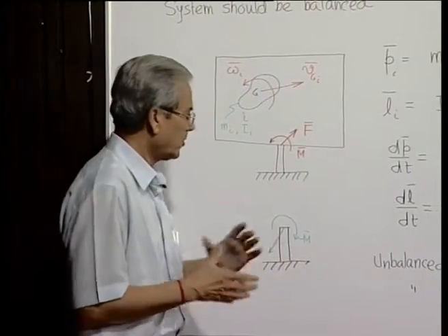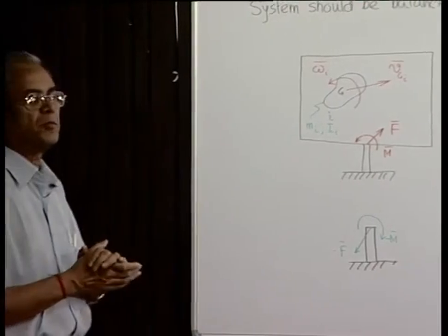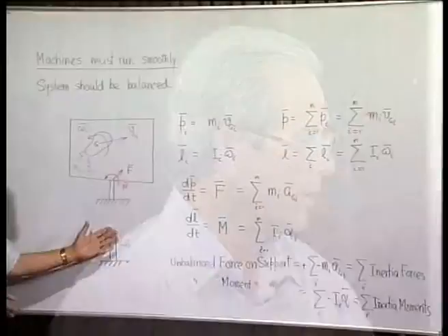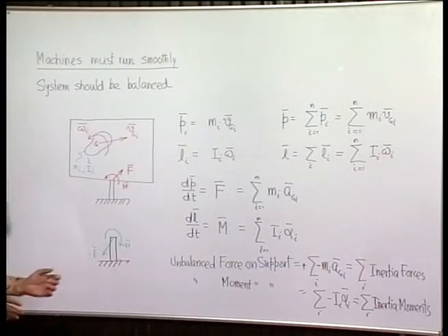So, now we will have to be further active in designing the machine, not just satisfying the dimensional requirements or being enough to produce the required motions kinematically. It is not enough for the components to have enough strength to sustain the forces and moments, but the mass distribution of the whole machine should be such that the support is not subjected to any dynamic force.